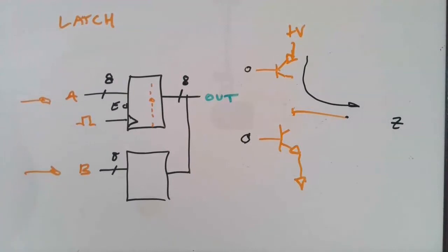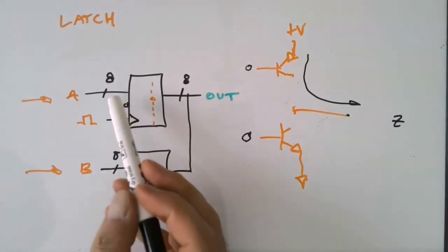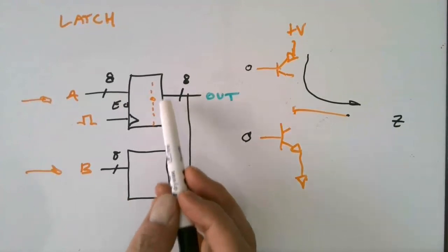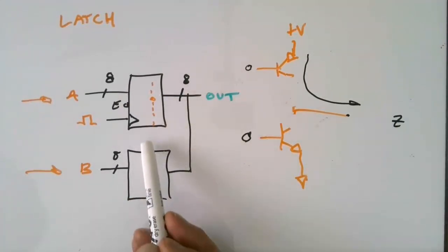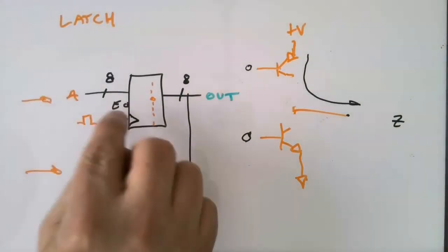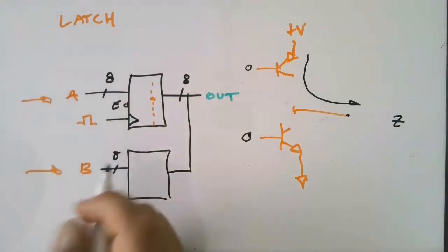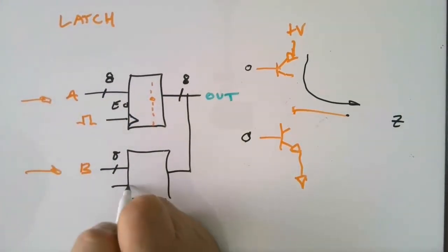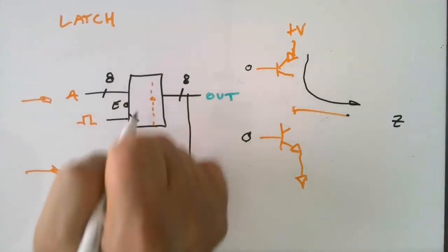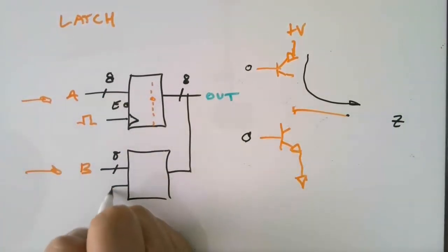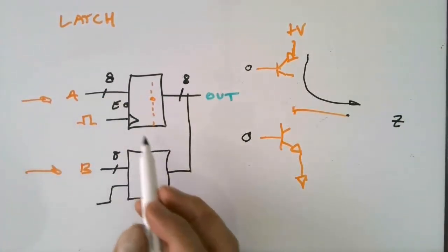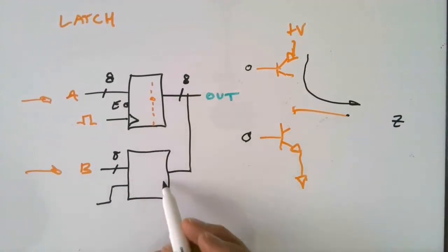So this is kind of a little bit of a diversion. It's more related to the hardware chapter. And if you look up tri-state outputs, you'll see a little bit more information on this. But the point is that this allows us a way of, if we take one enable line that's high true and another enable that's low true and connect those together, we could then basically decide which of these outputs is on at any time.